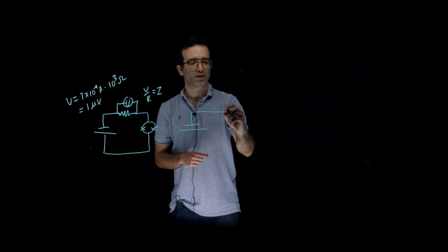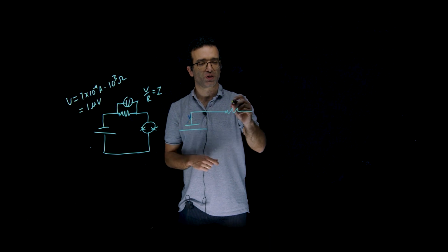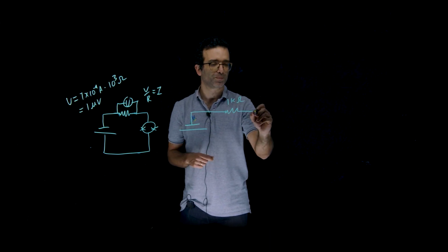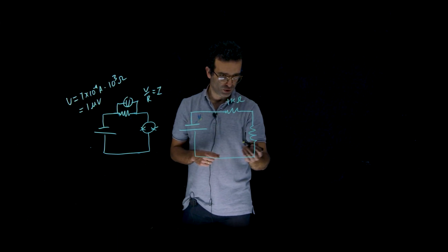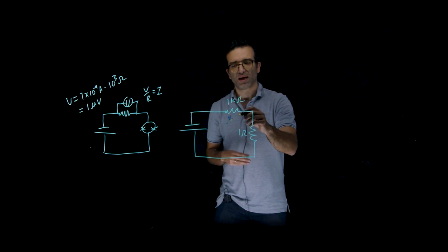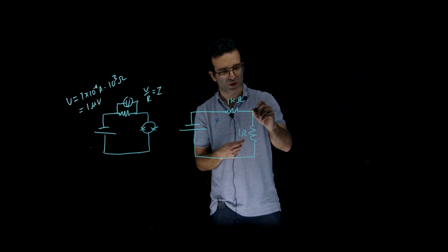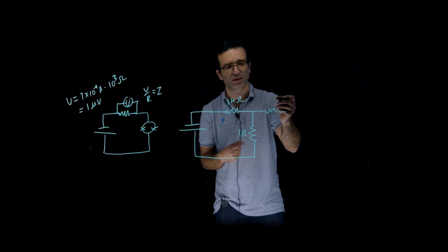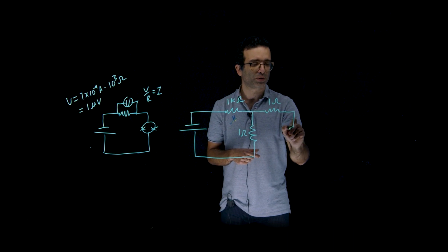So what we can do is a circuit like this, in which we put a certain resistor so that we are current biased. Typically we can put, let's say, 1 kilo ohm. And then here we put a very small resistor of the order of 1 ohm. All these wires are typically copper wires, low resistance, but they carry some resistance. So each time there is a piece of wire, I will draw some resistance. So let's say here another 1 ohm resistance. And here I put my SQUID